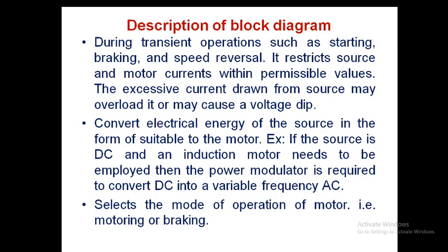Next one is it converts the electrical energy of the source into a form suitable to the motor. That's what I have told. If the source is DC and an induction motor needs to be employed, then the power modulator is required to convert DC into variable frequency AC.